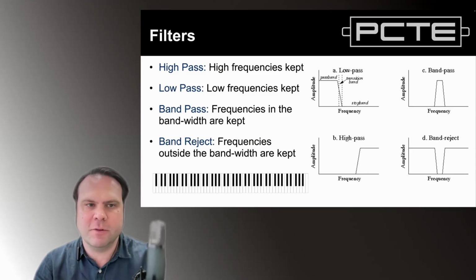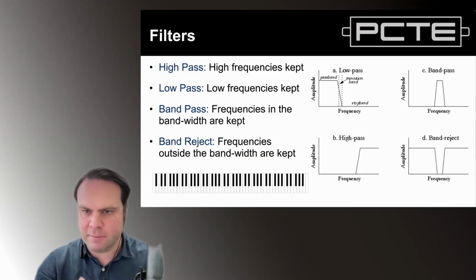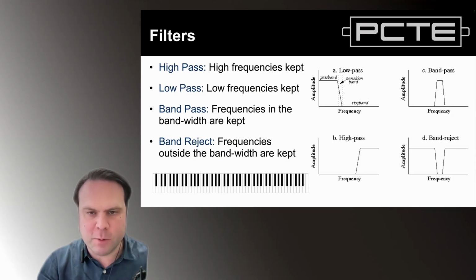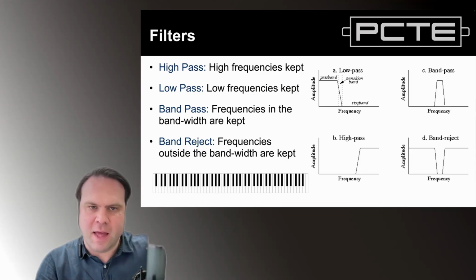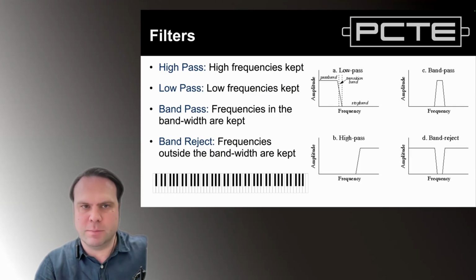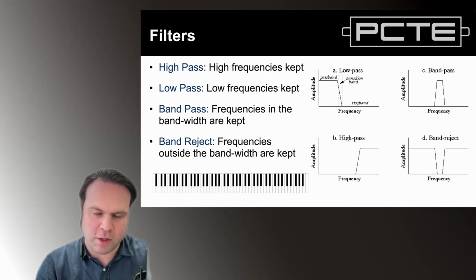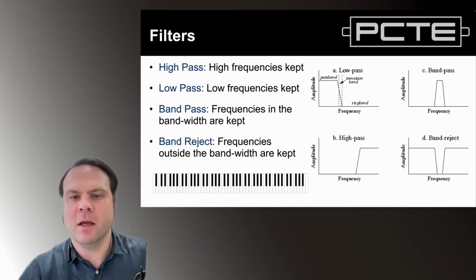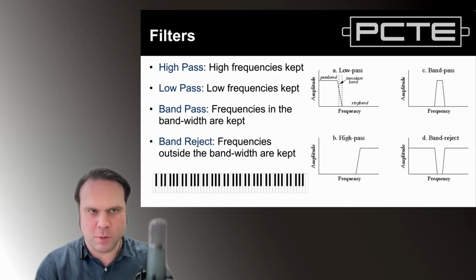So the purpose of a filter is to remove some of that frequency content from the measurement we take, to do exactly as I said, ignore the lowest frequency signals that would be caused by the motion of the sensor or the concrete structure under the strike, and provide us only the frequencies that relate directly to the geometry, the thickness, or the defect detection work that we're doing.